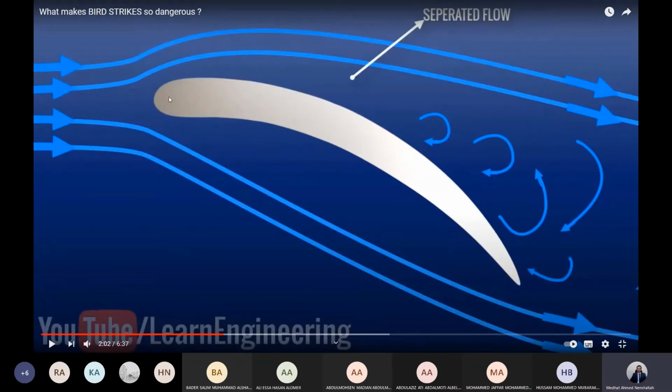So at lower flow rate, the flow will come with a different angle of attack. So some flow recirculation will be created here, and the back pressure will be created, and flow stall in this case.